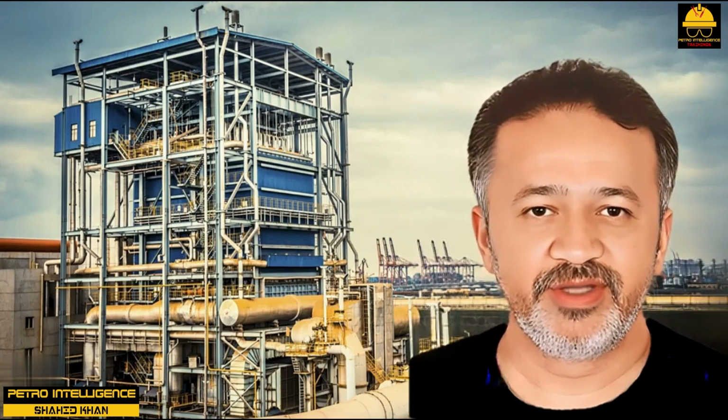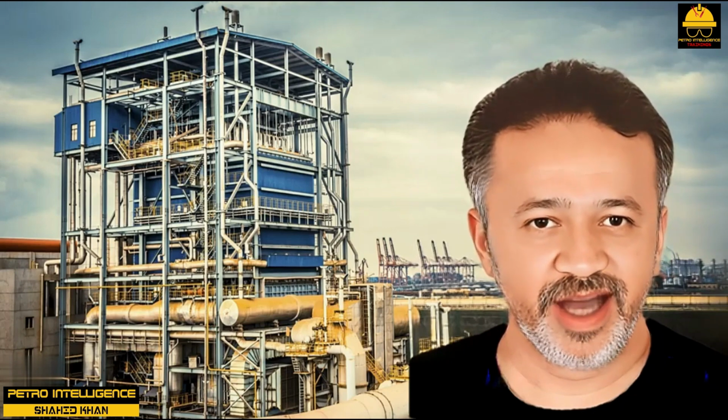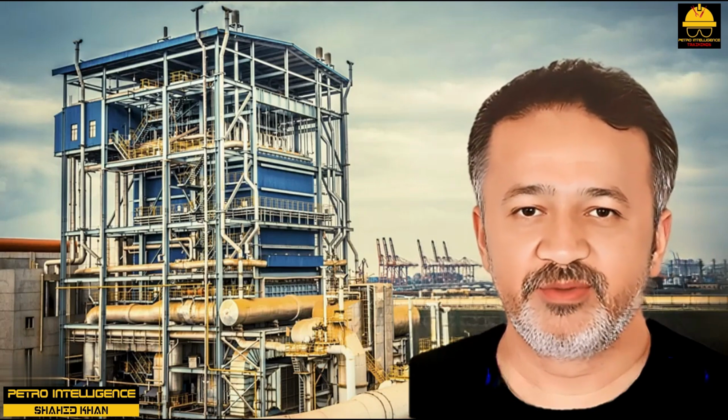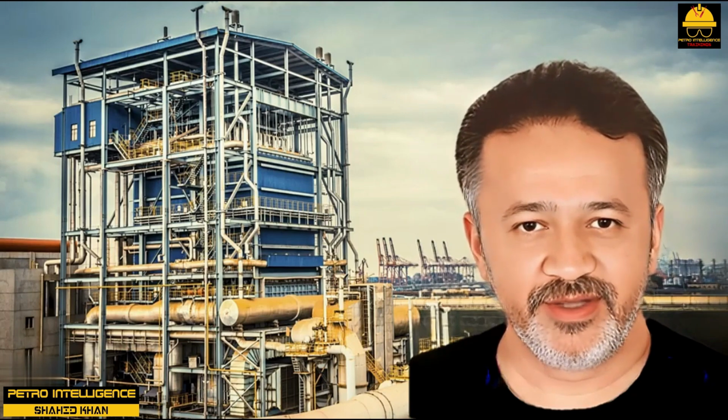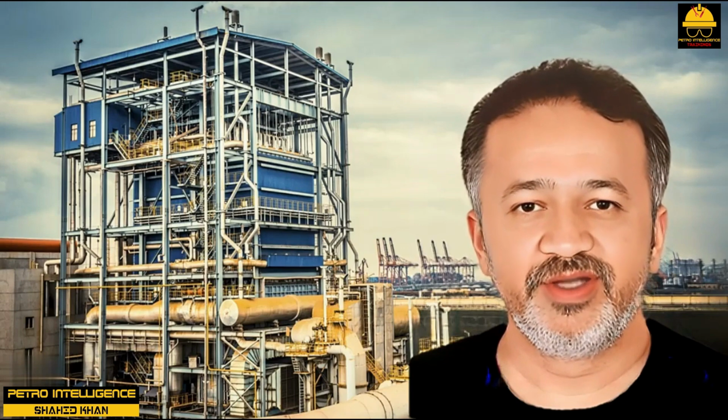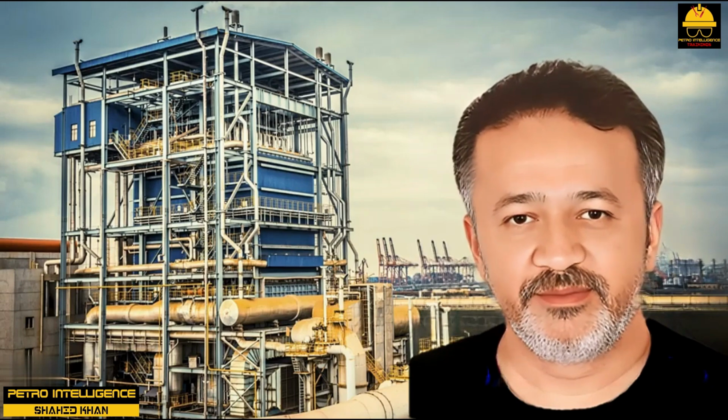However, if the controlling resistance to heat transfer is on the tube side, the increased outside surface area of the tubes does not improve heat transfer rates. Caution: if the shell side is subject to fouling, then dirt gets between the fins, in which case the heat transfer will now be worse than with smooth, unfinned tubes.